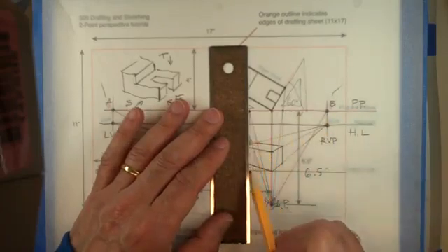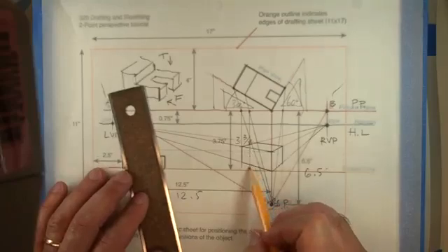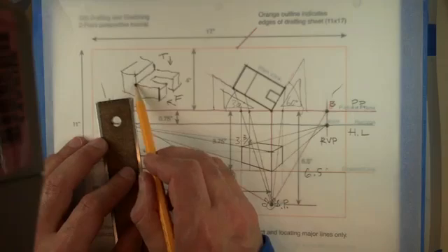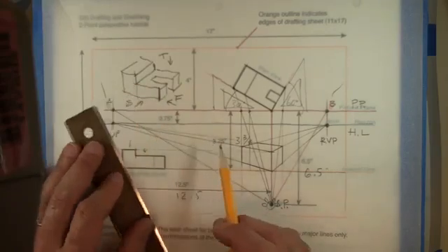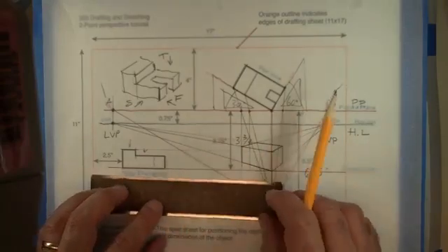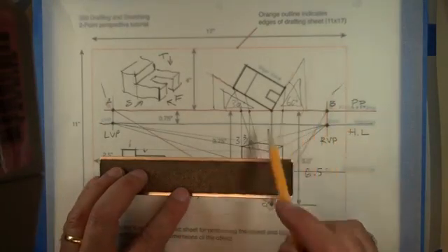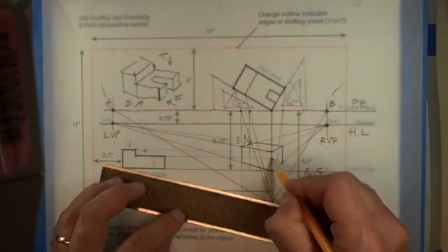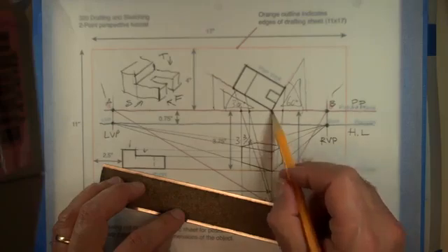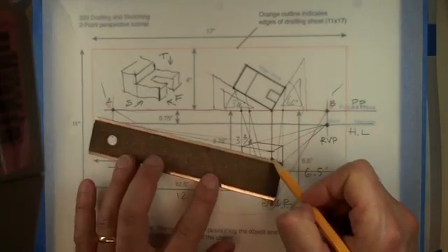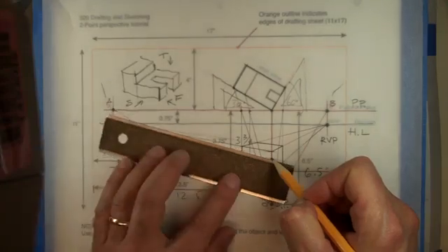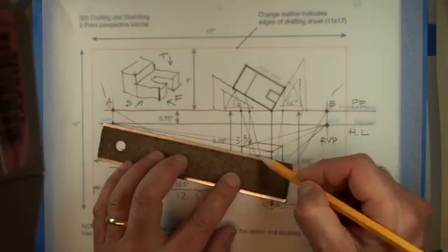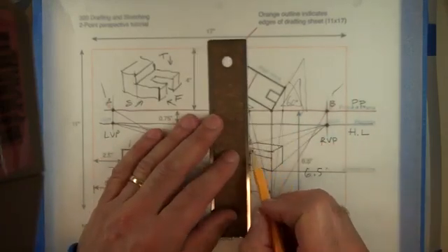And as I do that, what I get really is a line on the side, which would be this line. I really just need that little part, right? So to find that height there, I project the height of that step onto the edge, onto my leading edge right here. So I project that, I get the height, the real height, right? The true height, because that's touching the picture plane. From there I project, again, don't get confused with A, just go to the vanishing point. And when you do that, where they cross with my other line, I get the side.